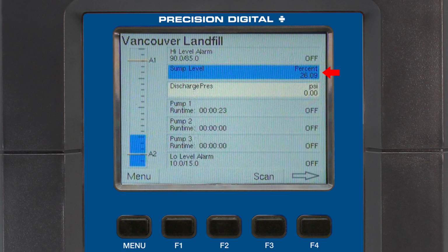This will prevent all the pumps from being called to run at the same time when power returns. The next time the level reaches the same 60% set point, pump 2 will turn on after its configured delay. This is the alternation of the lead pumps at the lower 60% set point. Pump 2 drains down to the same 20% point and then turns off. Pumps 1 and 2 will continue to alternate with each other without pump 3 ever turning on.